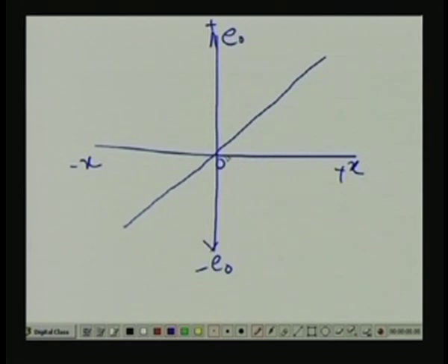As I told you, plus x and minus x are nothing but above null, or the one side of the null is positive. If one side of the null of the core movement is positive, the other side of the null we are taking as negative. So, you see we are distinctly getting a linear relationship, but along with the change in magnitude, I can now tell whether it is above null or below null by looking at the voltage. This is very important. If it goes below null, obviously what will happen? I will get a negative voltage.